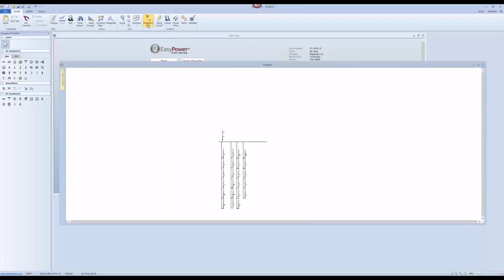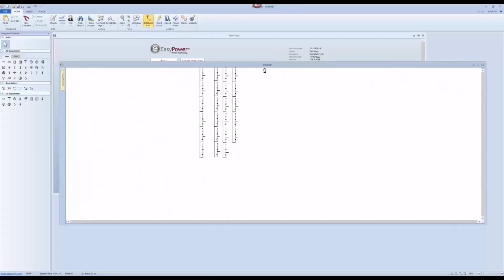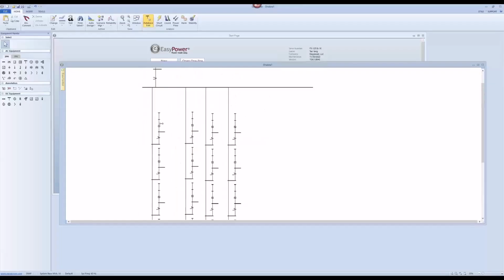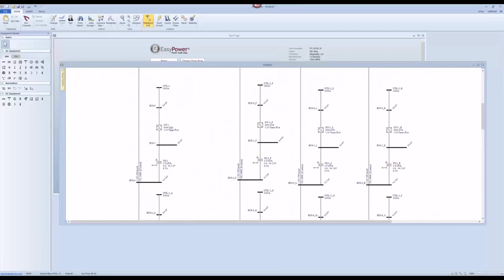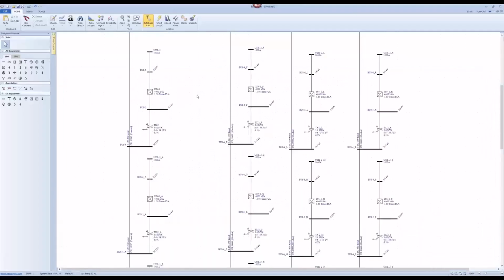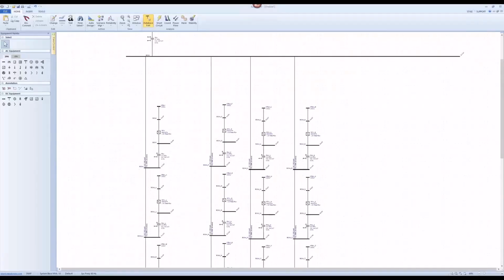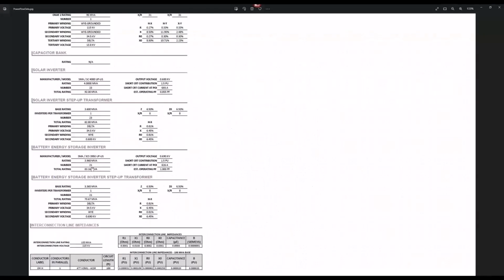Now, if you want, what we can do is very simple: we just repeat the same process we did just now to add the battery energy storage portion at the very right. So you copy and paste the design and then revise your harmonic current injection based on the energy storage inverter spec, and then revise the GSU rating and revise your inverter rating based on your power flow data for the BESS, right?